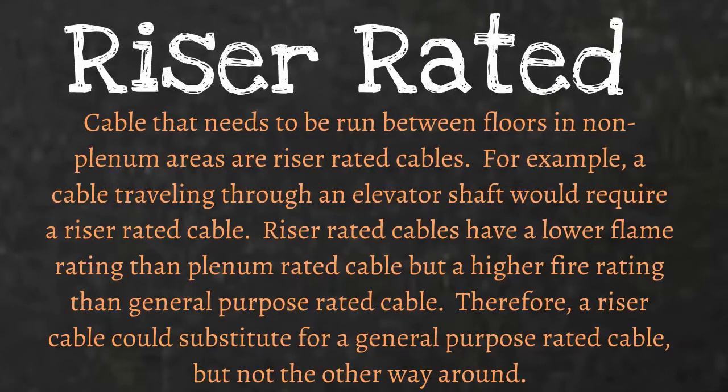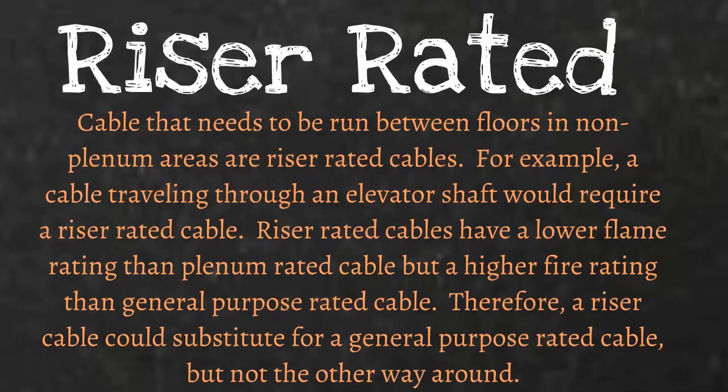Riser-rated cables. Cables that need to be run between floors in non-plenum areas are riser-rated cables. For example, a cable traveling through an elevator shaft would require a riser-rated cable. Riser-rated cables have a lower flame rating than plenum-rated cables, but a higher fire rating than general-purpose rated cable. Therefore, a riser-rated cable could substitute for a general-purpose rated cable, but not the other way around.